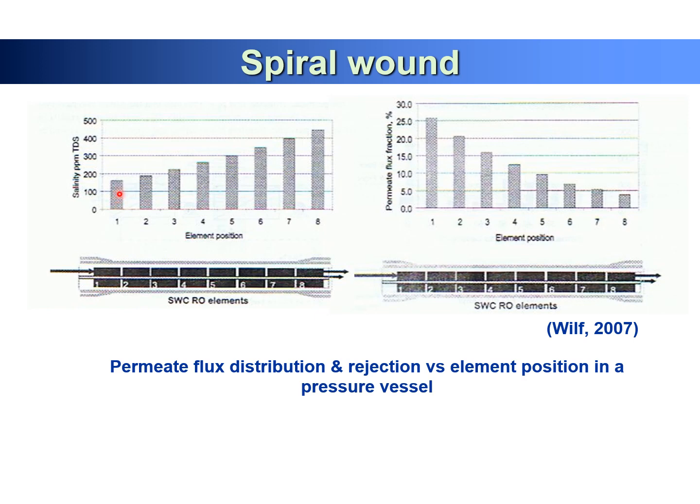You can see in the first element the permeate water concentration is around 150 milligram per liter, and at the end of the element, more than 400 milligram per liter of total dissolved solids concentration is coming out. So we mix all the permeate and then calculate the final concentration of our TDS.